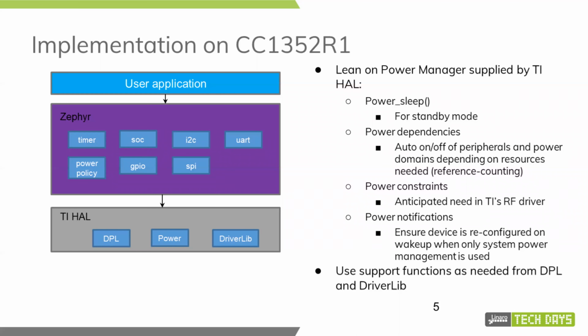And then there's a power notification feature, which allows the drivers to register a callback function with the power manager, so that when the device wakes up, it can be notified of that event, and it can go ahead and reinitialize the peripherals if needed. And this is because in the case where system power management is turned on, but device power management is not turned on, then the device drivers are currently not notified of these wake up events. And I'm sort of leveraging this to work around that fact.